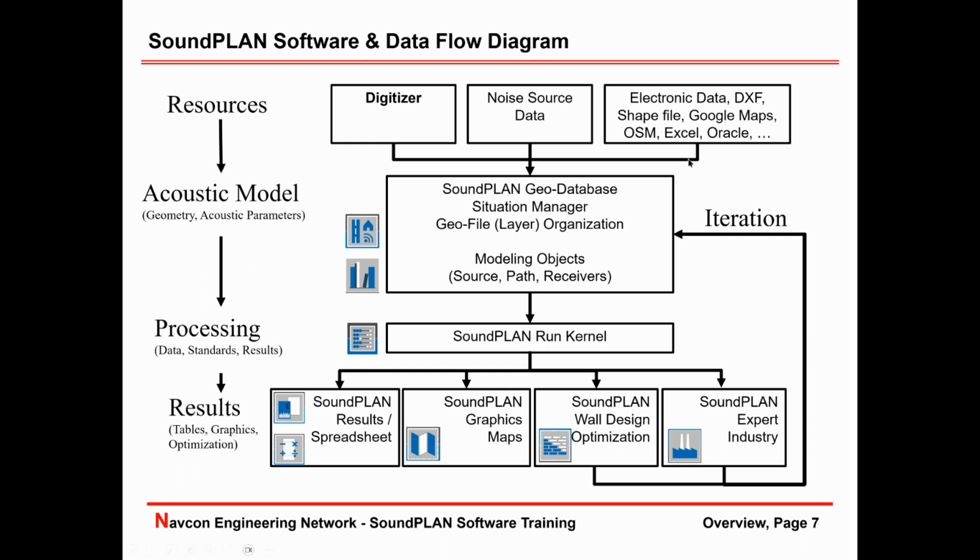All of this, of course, needs to be collected before we start with the project. Some of that is always available, like the Google Maps and the topography. We can get that information pretty much worldwide. OpenStreetMap could also be readily available. But in terms of the noise sources, we need to get that feedback either for traffic or for the source definition for construction or whatever model you're creating, the information about the noise source, sound power, or traffic information. All of the resource information will feed into the acoustical model.